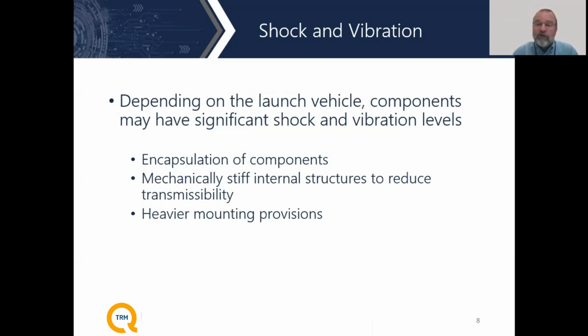So what we do is we go through some very detailed analysis to ensure that the parts will not be damaged by these very high levels of vibration and shock. We do things like encapsulate components. We design our structures so that they're mechanically stiff, to increase the first natural resonant frequency, therefore reducing stresses and strains on the solder joints.